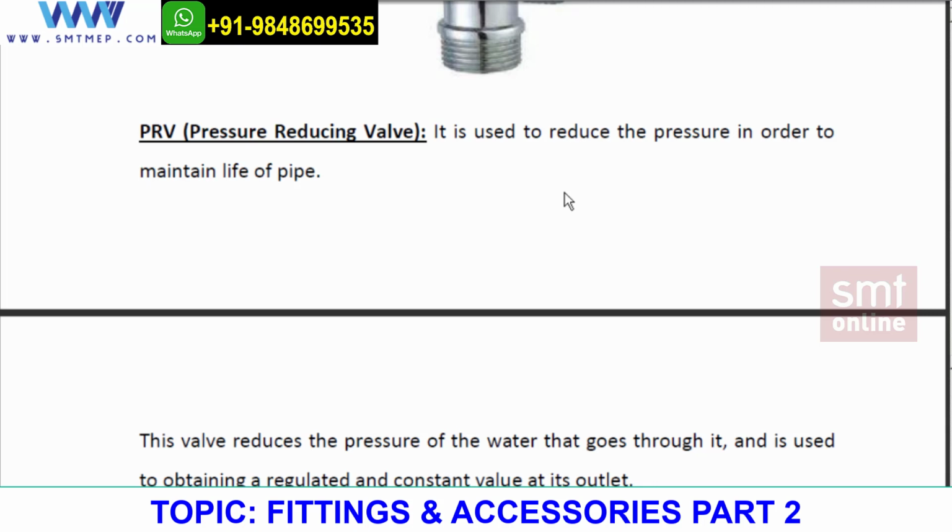Anish, I think you know this. Anish, at what value do you have a pressure reducing valve, because you use UPC, 60 psi? And as per IPC, from the International Plumbing Code, it is recommended if you have a pressure in a riser, because in a water main, that is a riser. So only in risers will you see this. You'll not see it inline, within the floors and so on. You'll not see a pressure reducing valve there, because where is the main source? Because of gravity only the pressure increases.